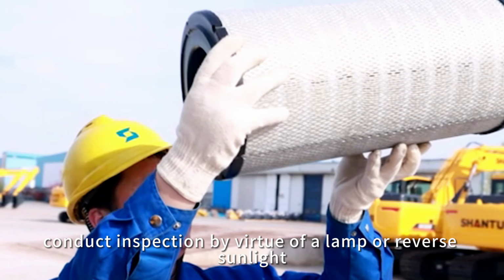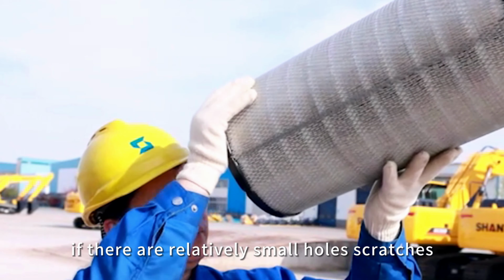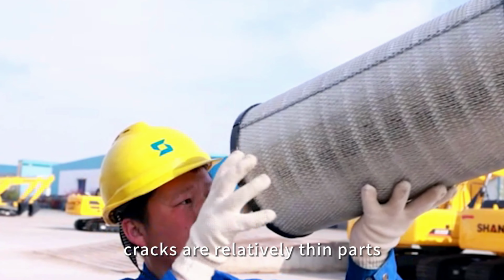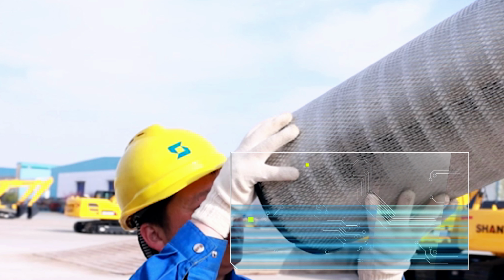By virtue of a lamp or reverse sunlight, if there are relatively small holes, scratches, cracks or relatively thin parts, the main filter element must be replaced. 4. After being cleaned for 6 times or 1,000 H, the main filter element and the safety filter element must be replaced.